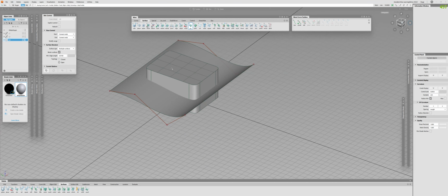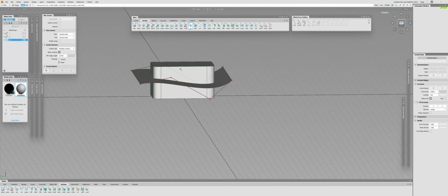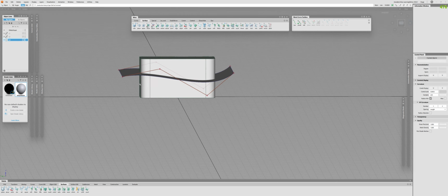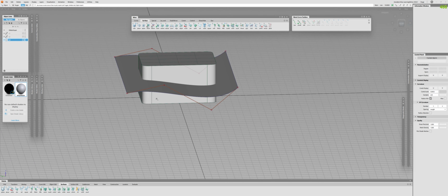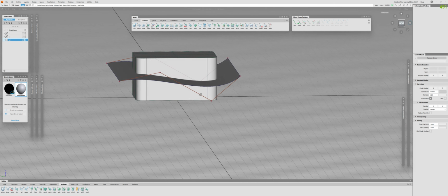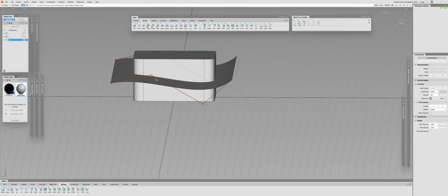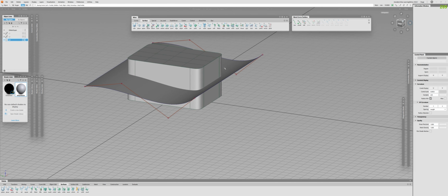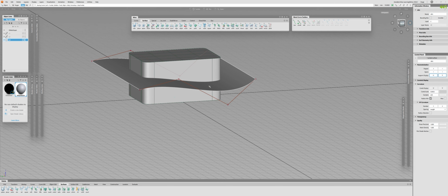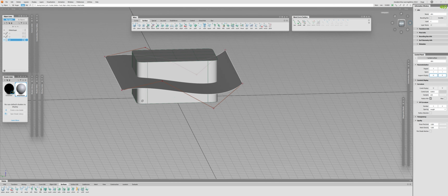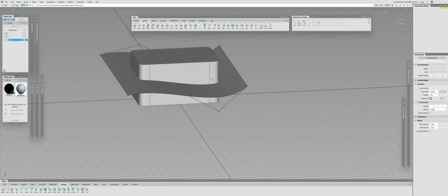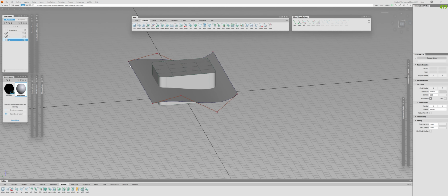So you will have the cutter, and then you place it where you want, and then you perform the cut. Now, the trick is that when you need these two objects to be separate, you intersect everything, then you trim, but not just trim, you trim divide, because you need these pieces separate, and then you duplicate the cutter again, because this cutter basically is a part shared by two pieces. So you need two pieces of them, so basically two parts, and then you project and trim both of them separately, which once again takes time.